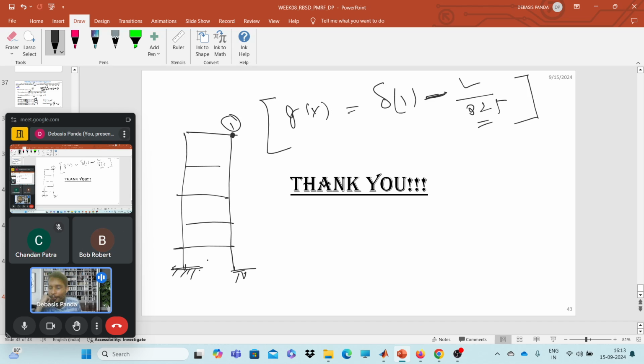After designing, you need to have samples of this top displacement. Now how can you get the top displacement values? Either you can model it using SAP or ANSYS, and from there you can get the value of the top displacement. Now if you have the limit state, you can analyze this design according to your serviceability limit state, or as per your ultimate limit state of strength. This is your explicit form of limit state.